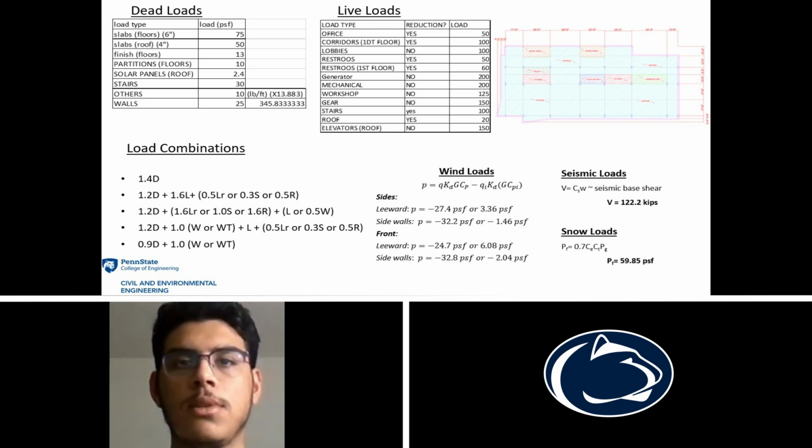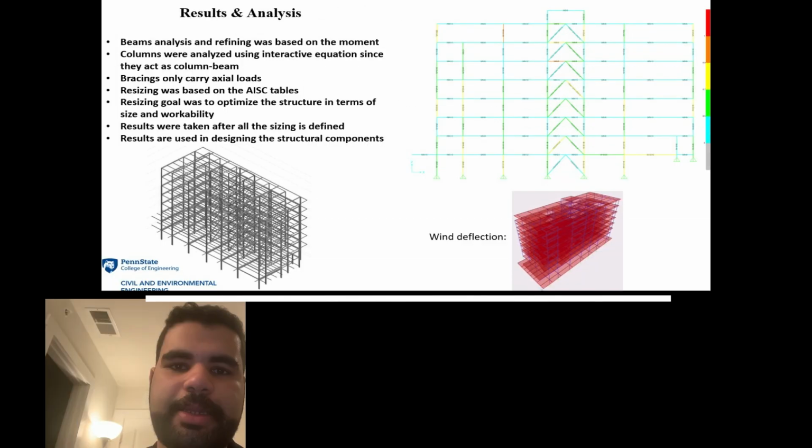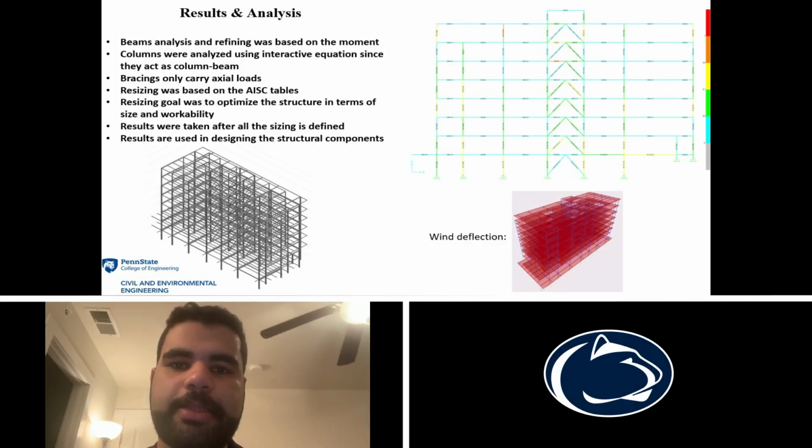Through calculations, we determined further loads such as wind loads, seismic loads, and snow loads, and gathered all the information we had to create the drawings seen here, which is a live load layout for a typical floor within our structural building. After the material definition and calculating the loads, they are applied in SAP2000.